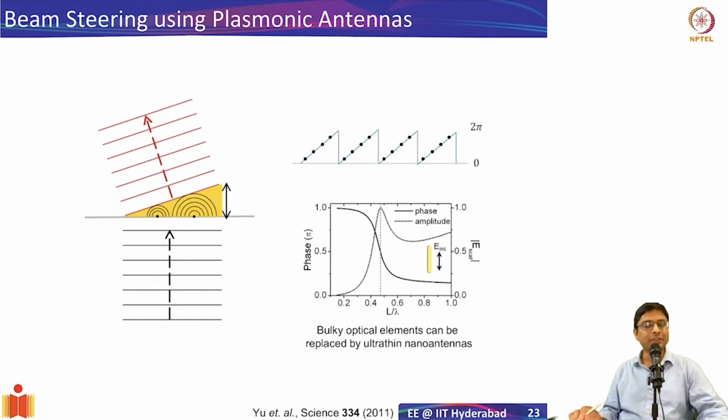If we were looking at traditional optics, we'd have to go back to the fundamental principles. One of the fundamental principles of wave propagation is Huygens principle, which says that every wavefront introduces secondary wavefronts, and then those secondary wavefronts propagate in a spherical fashion. For example, this beam will introduce a secondary wavefront here, and that will start propagating in wavefronts like this, and another point will again contribute another secondary source. All of these wavefronts will propagate, and eventually you will have an overlapping. The overlap of the phase fronts is what defines the direction of the beam, and that is how we get the beams propagating at an angle. But how do we achieve that?